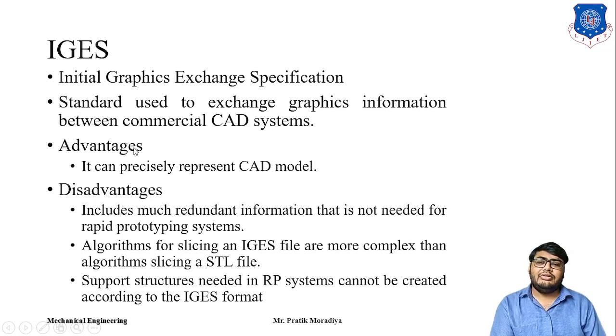Now there are also some disadvantages of IGES when we talk about rapid prototyping or additive manufacturing techniques. The most significant, the most prominent one, is the redundant information, because when we are making a prototype out of an STL or any file, all the information we need is just geometry, or specifically 2D data. But the IGES format will have much information which is not needed for rapid prototyping.